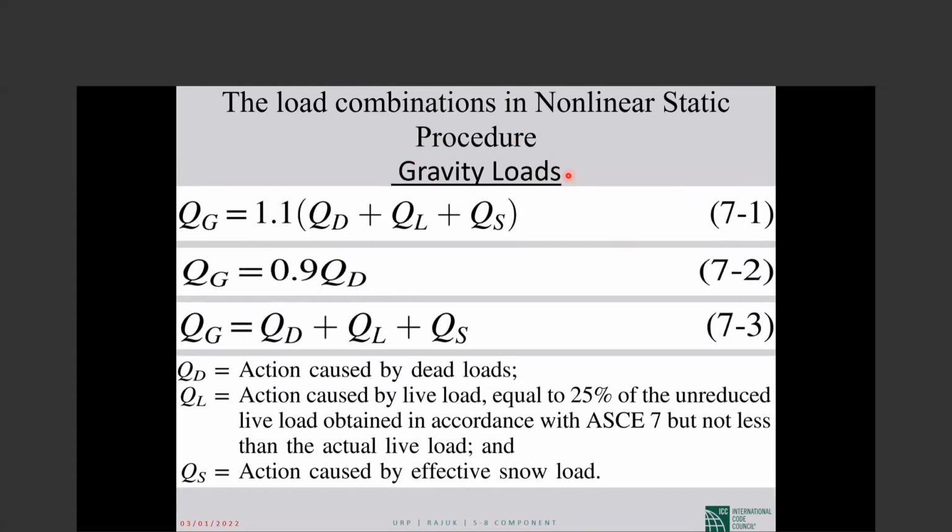Otherwise, it's not possible to do separately and sum the results, because this is nonlinear and superposition is not valid. The result with and without gravity loads, when we sum them, won't be the same.